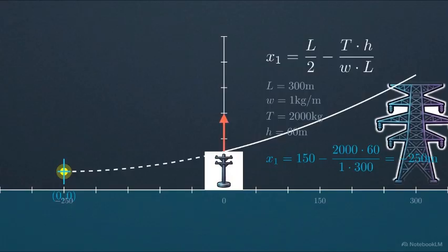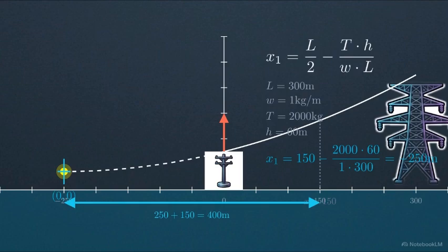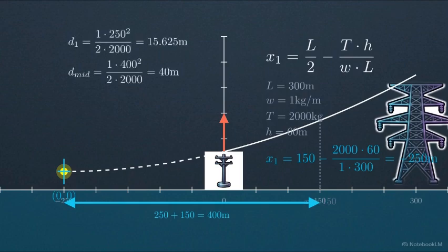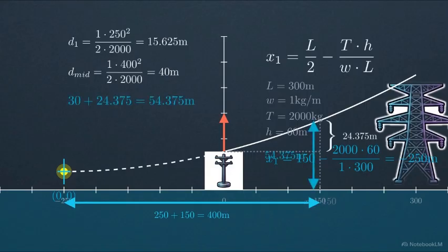The lowest point of this mathematical curve doesn't actually exist between the two towers. It sits 250 meters completely outside the physical span, effectively pulling upward on the shorter tower. Engineers map this invisible, virtual lowest point because they need it as a rigid mathematical anchor. Measuring back from that negative position, they can accurately verify that the midpoint of the wire hangs exactly 54.375 meters above the river.